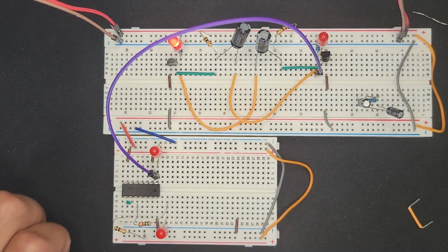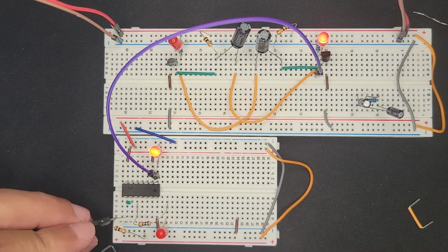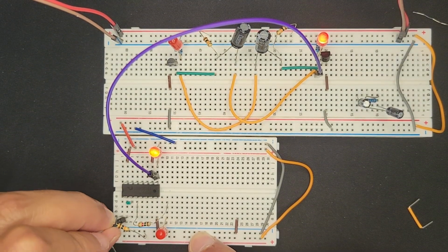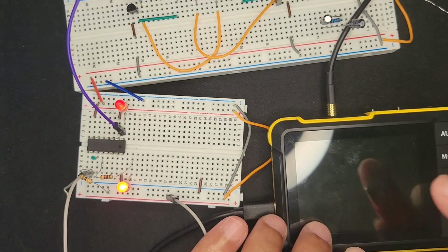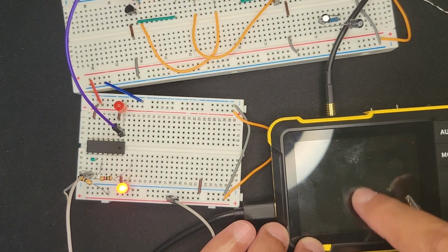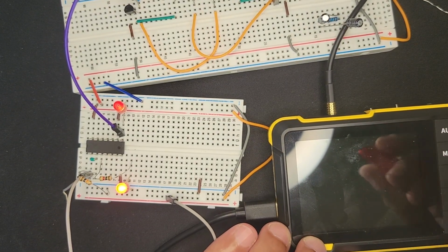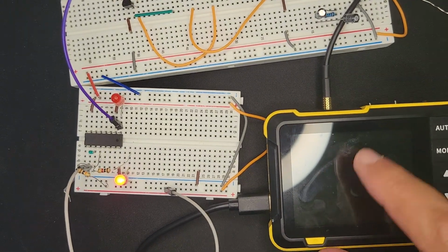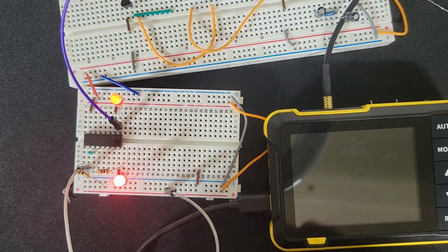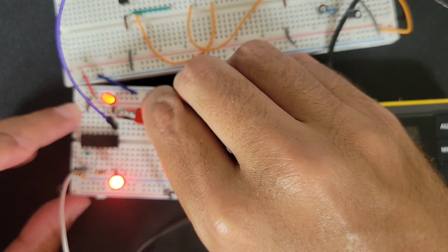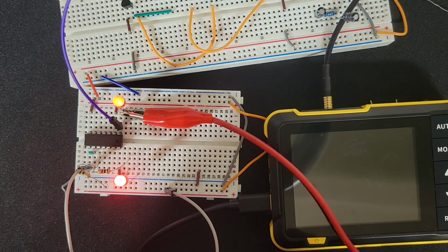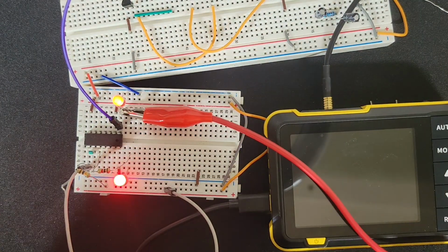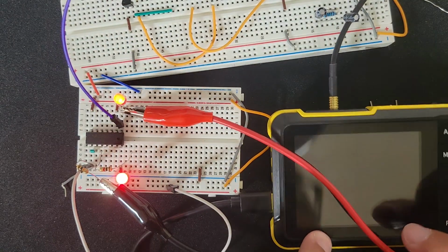I think what I'm going to do real quick is use this cable instead for this input here, so I could just easily plug it out and plug it in. So I'm going to use the oscilloscope and check out the shape of the waveform that's coming from the clock to see if that's causing it. Maybe it's too slow of a curve or something. I'm going to turn off my light so you can actually see this. And I'm going to plug the positive onto this LED's probe right there coming from the clock signal. And then the other one I'll just put to ground, like right here, and then turn it on.